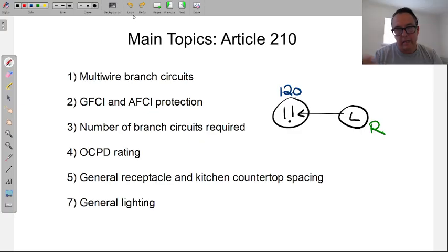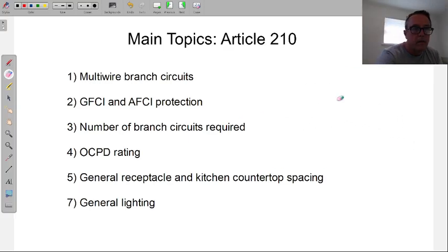And it's in outlets because, you know, the oven could possibly be unplugged, but nobody's unplugging an oven or anything like that. People are unplugging computers, lamps, things like that. So arcing happens. Arcing can potentially cause fires. And so these arc fault protection breakers, which we'll talk about, protect the circuits during those events. All right.